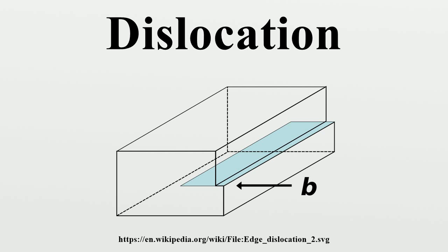Tangles of dislocations are found at the early stage of deformation and appear as non-well-defined boundaries. The process of dynamic recovery leads, eventually, to the formation of a cellular structure containing boundaries with misorientation lower than 15 degrees. In addition, adding pinning points that inhibit the motion of dislocations, such as alloying elements, can introduce stress fields that ultimately strengthen the material by requiring a higher applied stress to overcome the pinning stress and continue dislocation motion.